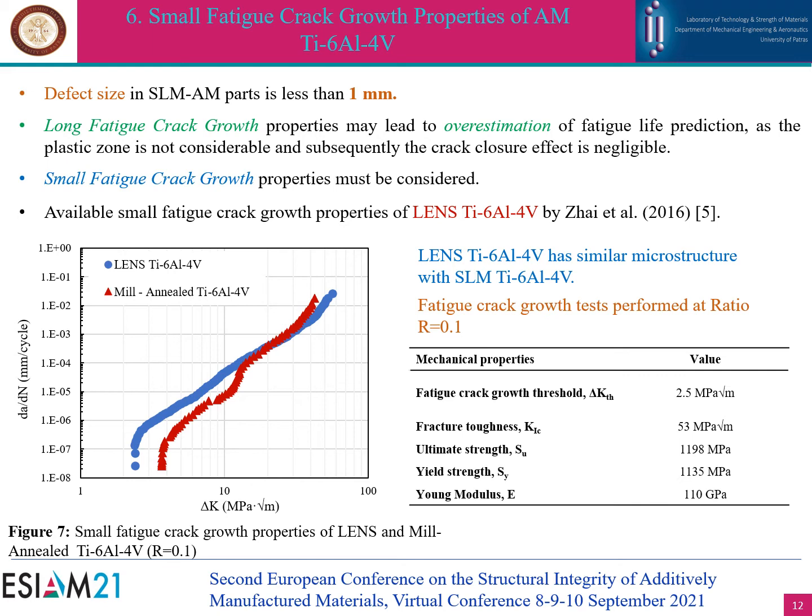In this work, the available small fatigue crack growth properties of wrought Ti64 from the open literature were used. Although wrought Ti64 presents some differences with the SLM process, the resulting microstructure is similar. Thus, wrought properties can be used in the fatigue life estimation model.